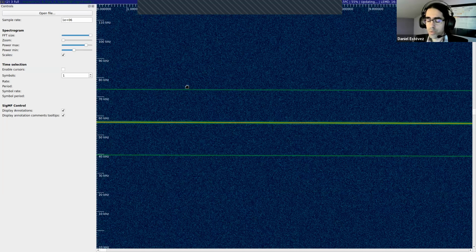This is the GBT recording. And something that needs to be kept in mind is that radio astronomy receivers are intended to receive rather weak signals. So when you have a really strong signal, such as the TGO signal here, you might have saturation on some of the digital stages. You might have intermodulation on analog stages.